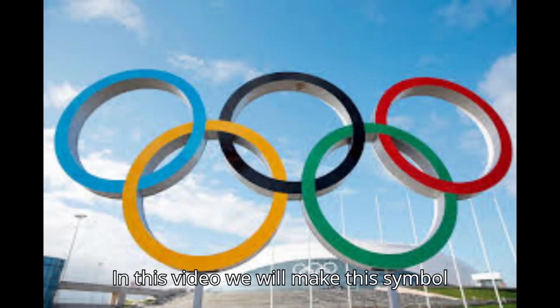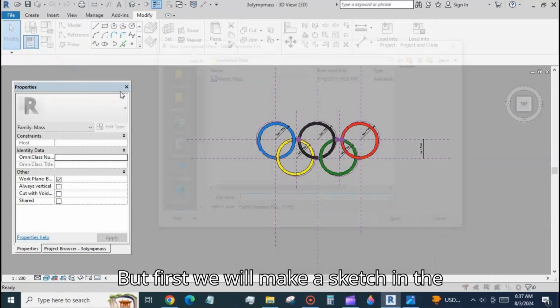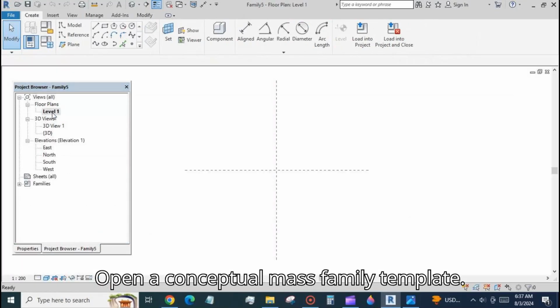In this video we will make this symbol, the Olympic rings. We will be using an adaptive family to create the repetition. But first we will make a sketch in the conceptual mass family. Open a conceptual mass family template.